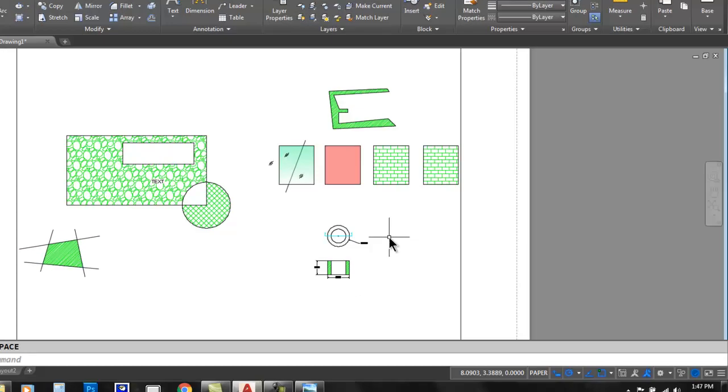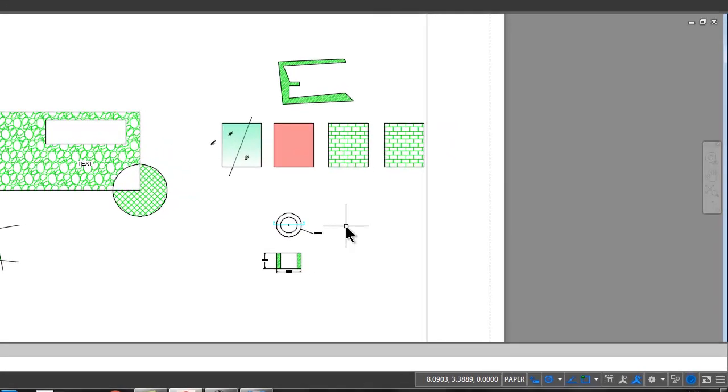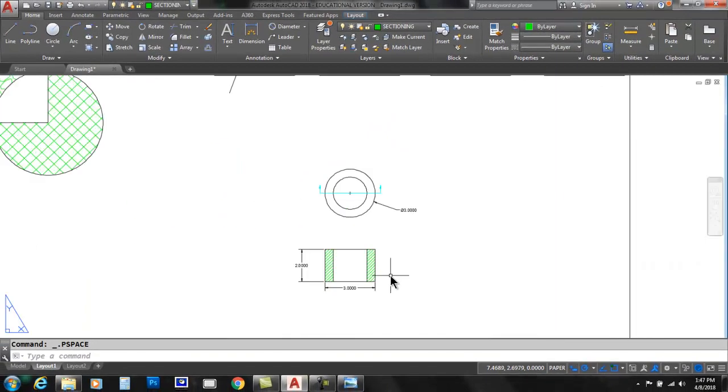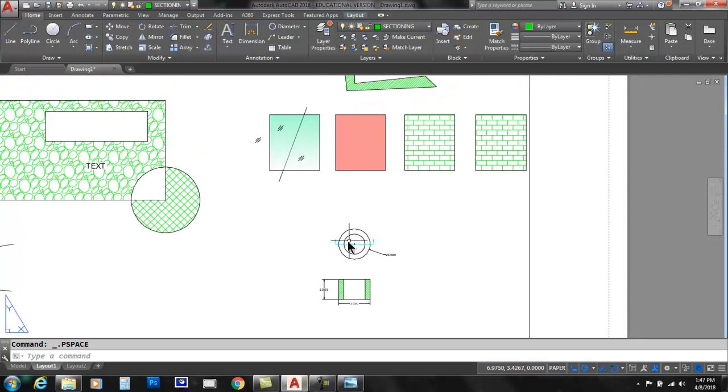Alright, so let's take a little closer look and say, for a good presentation, let's say that I want my black lines to be thick. I don't want the light blue, so I can barely see it. I want to reassign the light blue to be a darker blue. Okay, all of that would be done in a color table file.